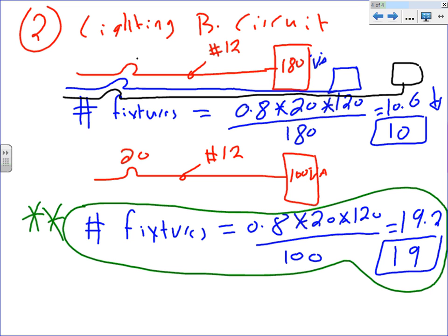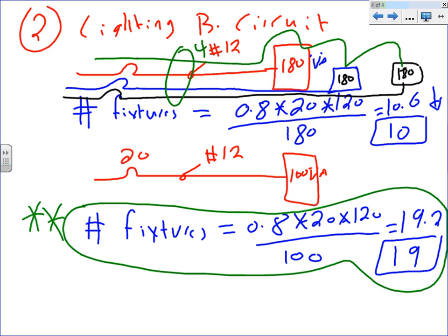And if you remodel the building, guess what? You remodel the branch circuits. So here's another circuit. Here's another 180, which could be any one of them, guys. And then the best scenario again, and I know the harmonics and all that stuff, is to bring in neutral and neutral and neutral. So here's your three-phase, 4-conductor, number 12, three-phase lighting circuit, and you can feed from these based on the scenario.